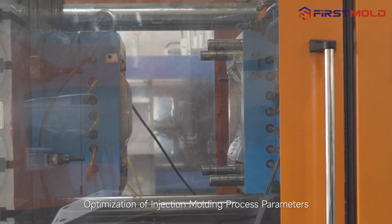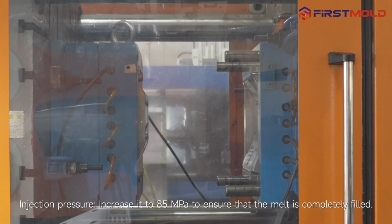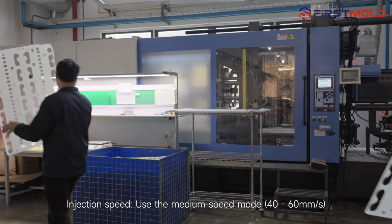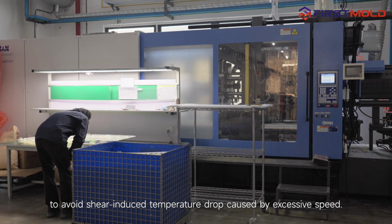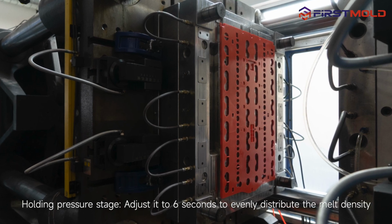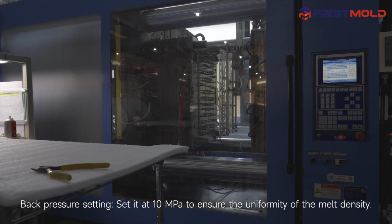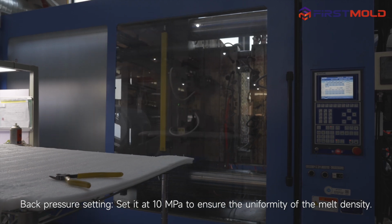3. Optimization of injection molding process parameters. Injection pressure. Increase it to 85 MPa to ensure that the melt is completely filled. Injection speed. Use the medium speed mode, 40 to 60 mm/s, to avoid shear-induced temperature drop caused by excessive speed. Holding pressure stage. Adjust it to 6 seconds to evenly distribute the melt density and reduce internal stress. Back pressure setting. Set it at 10 MPa to ensure the uniformity of the melt density.